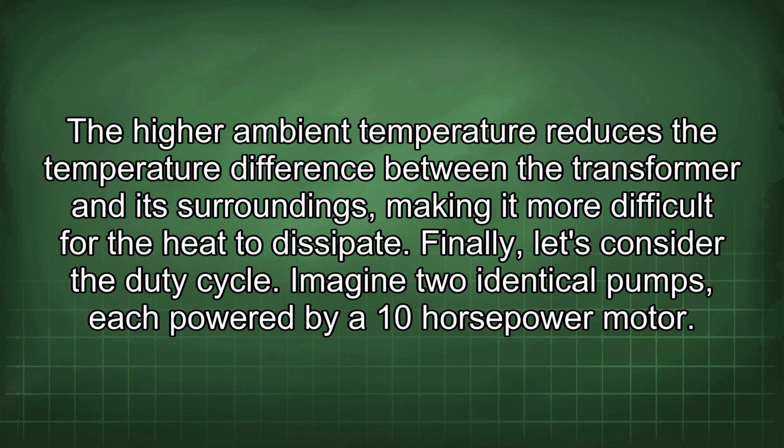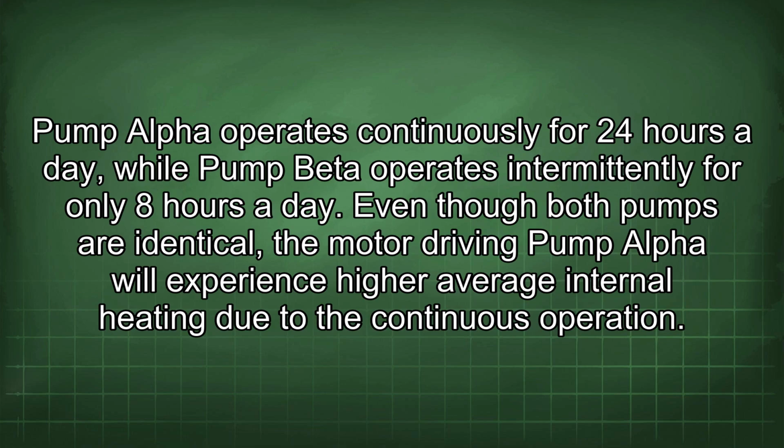Finally, let's consider the duty cycle. Imagine two identical pumps, each powered by a 10 horsepower motor. Pump alpha operates continuously for 24 hours a day, while pump beta operates intermittently for only 8 hours a day. Even though both pumps are identical, the motor driving pump alpha will experience higher average internal heating due to the continuous operation.